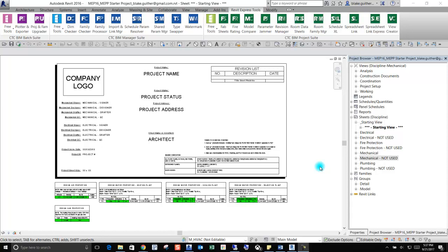It's helped to show people what you can do with a standardized set of shared parameters. So with that regard, there was a couple things we took into consideration when we updated this shared parameter list for this mechanical and electrical shared model productivity pack. One was preserving proper data types. Very important to be able to use things in calculations, to be able to trust the information in schedules.